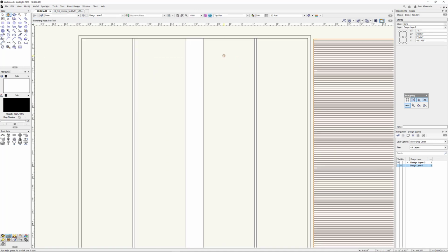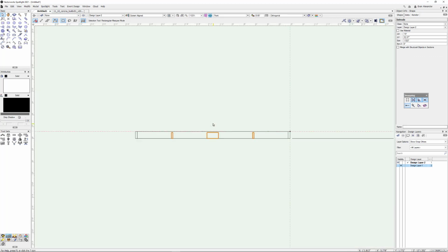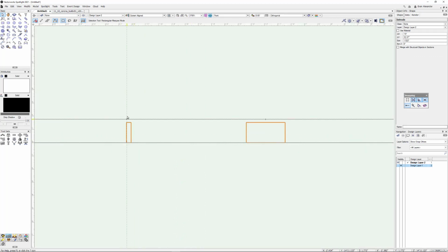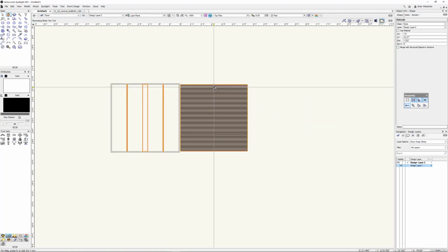Okay, so now these guys here, we want to extrude this. Now this is what it was before when we did the outer frame, but I want these to be not quite as deep because we want these to sit on top of these guys. So let's subtract 1/4 inch from this. If we look, you can see that here's the back, we've got this 1/4 inch depth that we're going to use. And so our tiles are going to sit right there, so everything will be nice and flush in the front. And I know, this is kind of weird, isn't it?